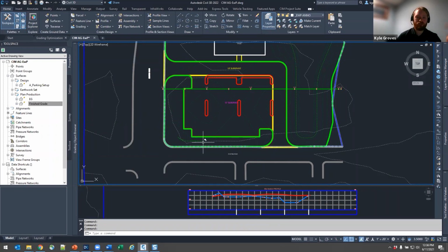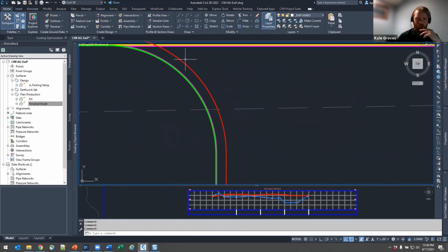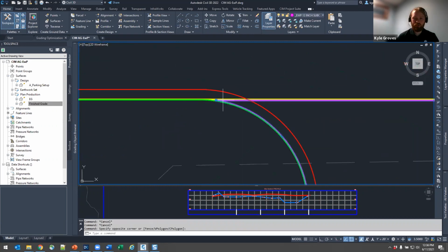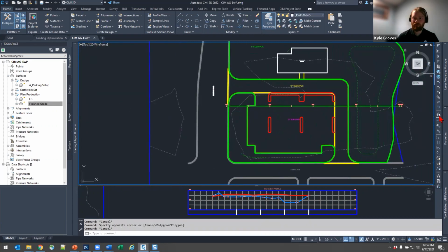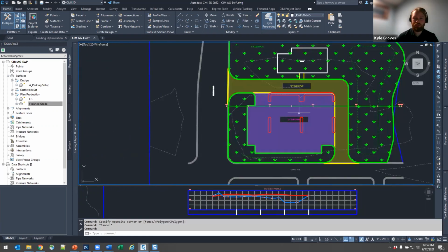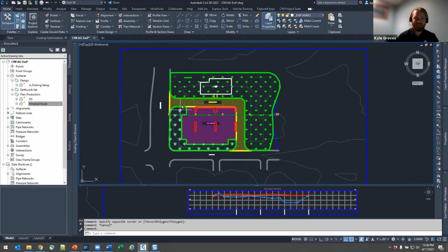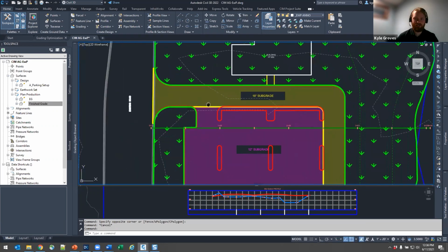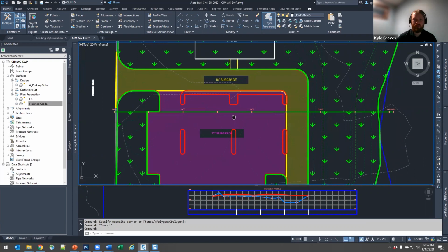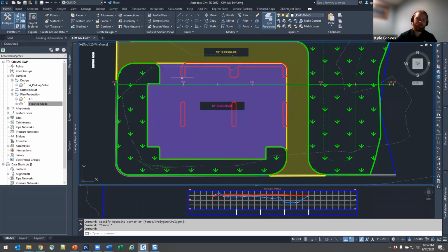It just produces your boundary, nothing in the middle. So on this, I have some landscape. I have a standard duty pavement in my parking area. Actually, there's one more layer we need, which is our subgrade patterns, because hatches are nice. So our green space has that green grass hatch. The transparent yellow is our heavy duty pavement. This is our commercial drive, our trash trucks, our delivery vehicles. And then our standard passenger car parking is just going to be a 12-inch composite material depth for that area